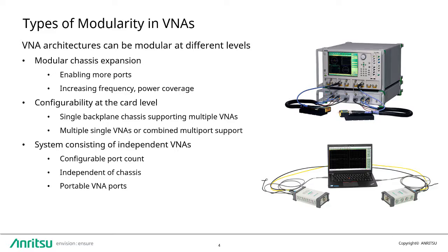typical non-modular integrated VNA. Modular by card, where each card is a separate instrument that is used in conjunction with a system controller and card cage, like PXIe or AXIe based instruments. Modular by standalone instrument, where separate instruments in independent packages can be configured together to create larger VNA systems without the need for a backplane or base VNA.